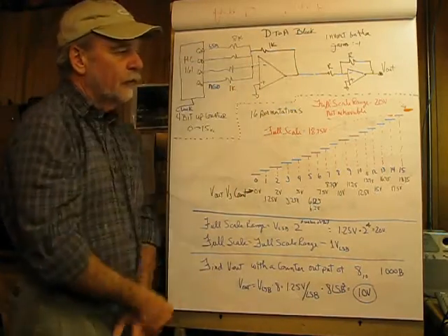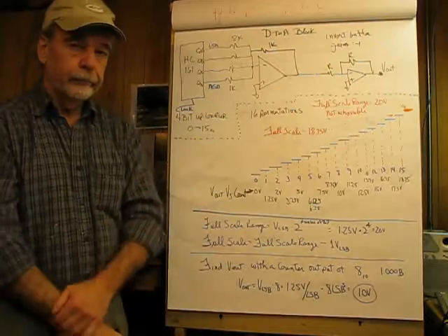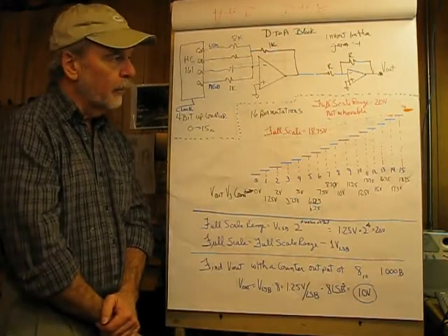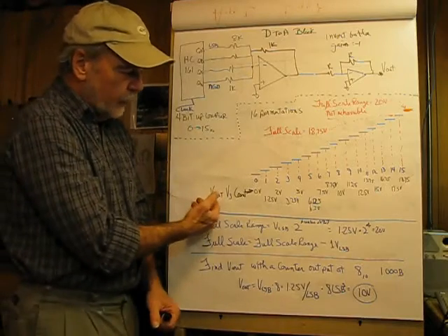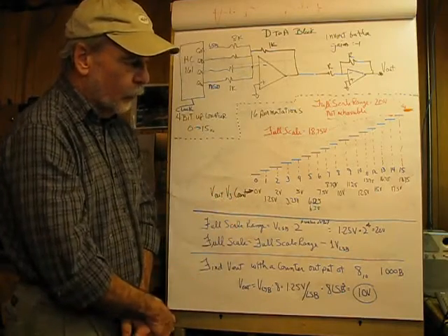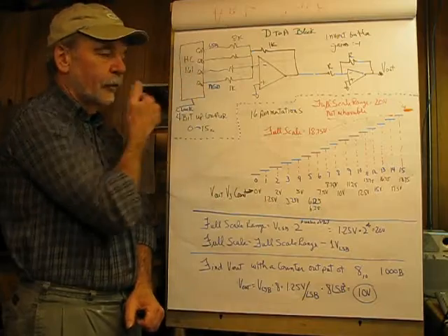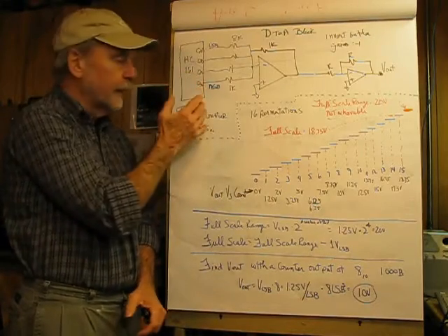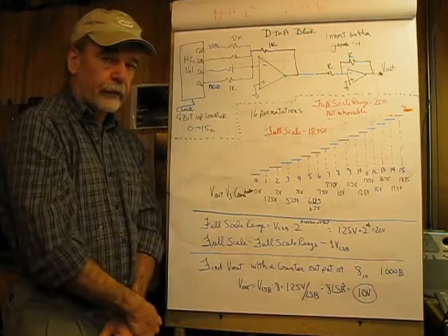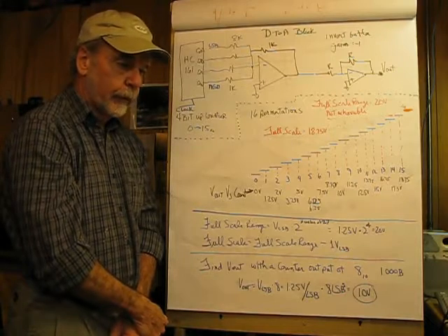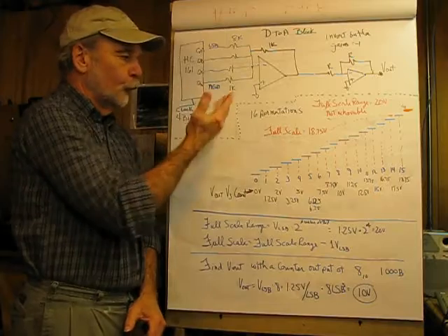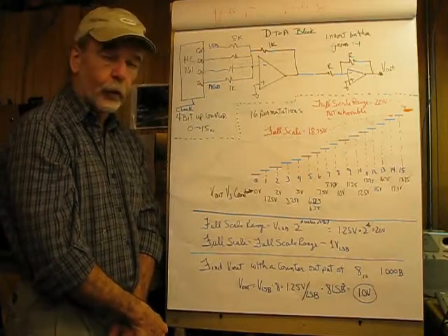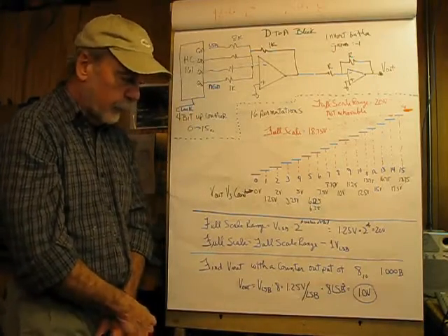We have an inverting summer and then a buffer here with a gain of -1. What we're using is 10 volts, by the way, so this is not realistic. This device is rated for 5, I believe, with a breakdown absolute max of 7, but I'm going to use it with 10 volts here so we can continue on with our example.